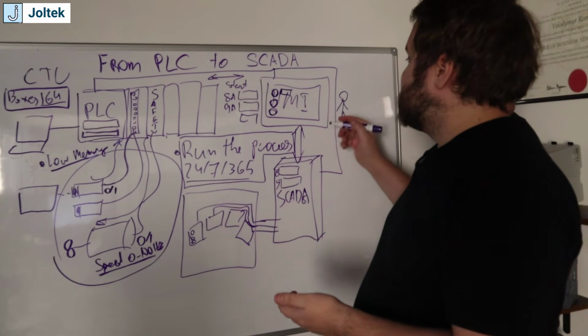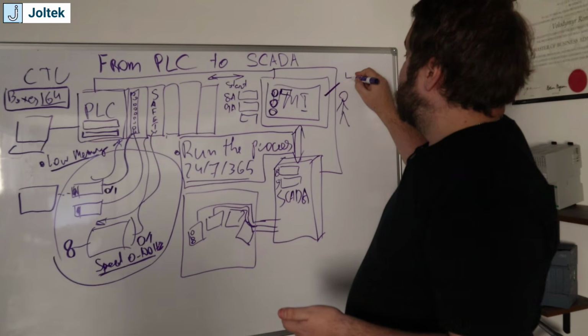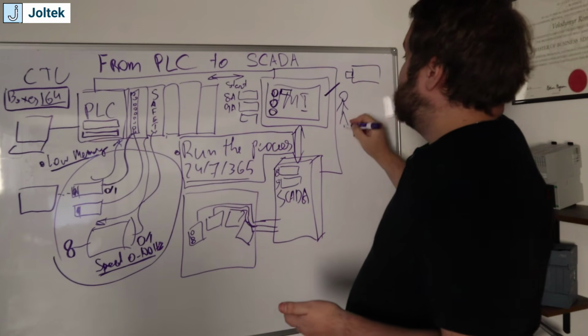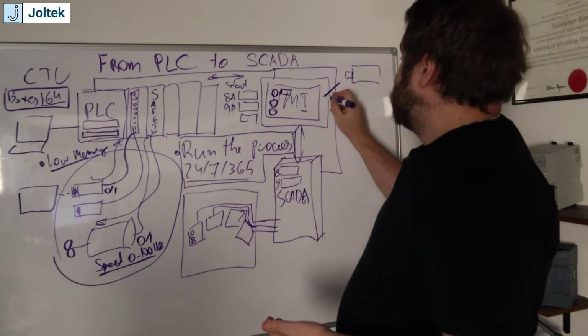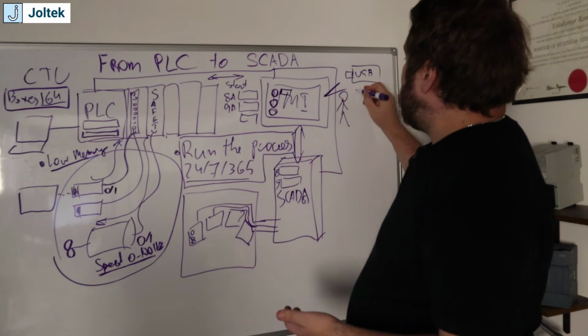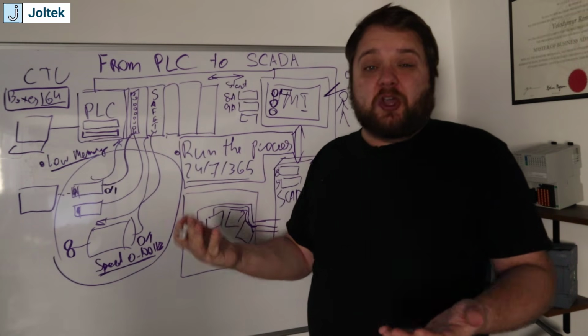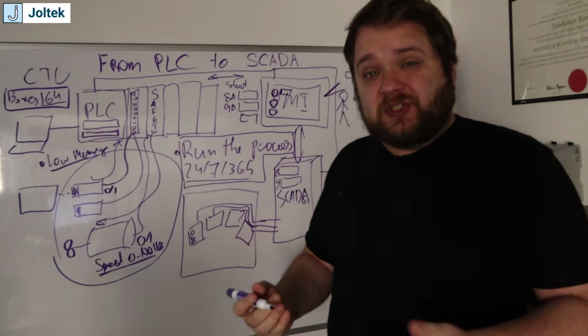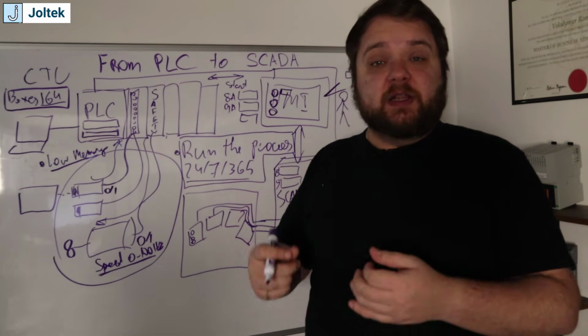There are of course some nuances, and I've talked to many manufacturers about this. You can plug a USB key into your HMI and retrieve some of the information. You can also use an SD card, which is a common occurrence for smaller machines. If you want to create a backup of the last week's operation, that is perfectly fine.